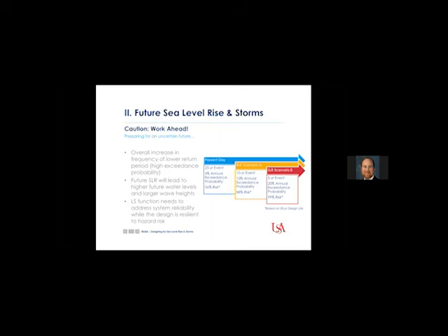But think in terms of how sea level rise will change our risk over time, and also climate change impacts like increasing storminess. Because sea levels are rising over the life of a project, and because the storm profile may change over the life of a project, we're going to have changing risk. And so consider this example where in the present day, we have, say, a 25-year return period event that might serve as a design basis for a project. Then that's got a 4% annual exceedance probability.